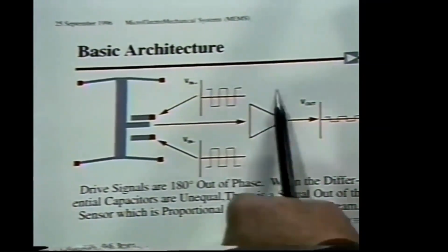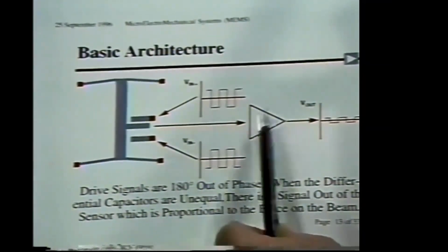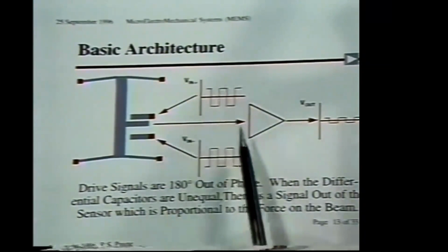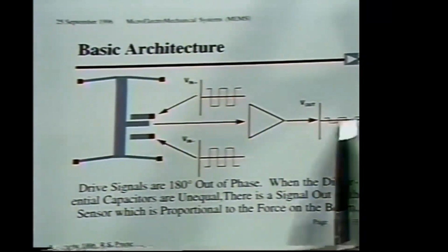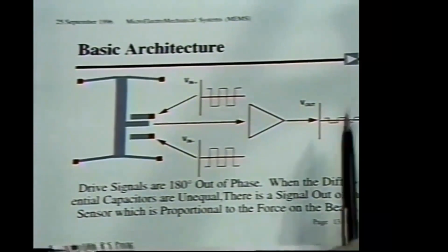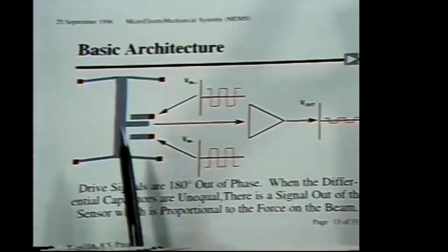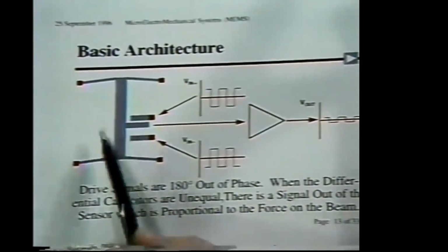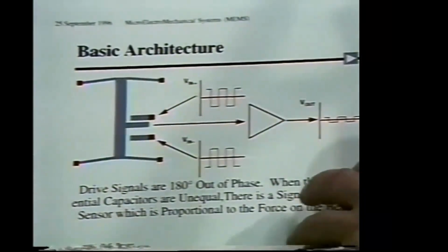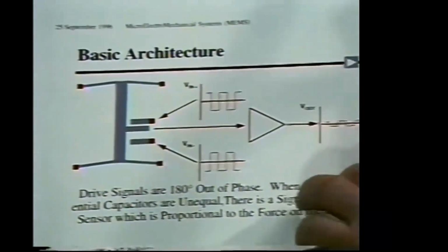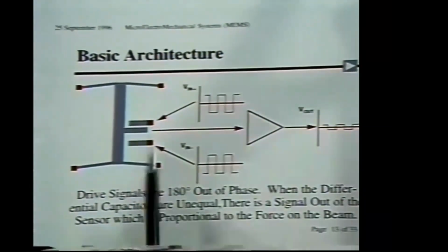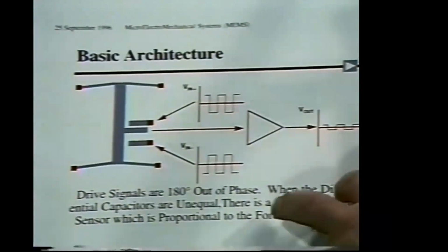Those signals are then demodulated or amplified somewhat, and the phase of the larger capacitor comes out, and the amplitude, due to the very small displacements, is linear in displacement. So this is really a displacement transducer with a mass. A proof mass is displaced against a spring and detected electronically. It's very, very sensitive. The displacement transduction of the airbag sensor is under an angstrom. It's about a half an angstrom that can be sensed. That's the equivalent displacement noise within the device.